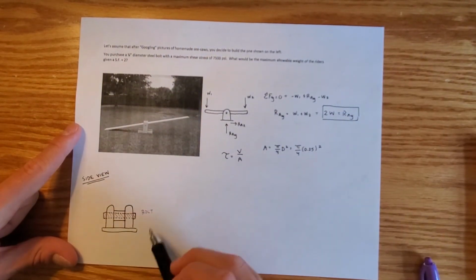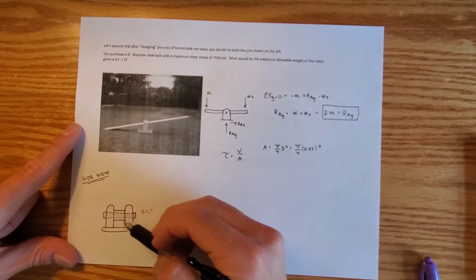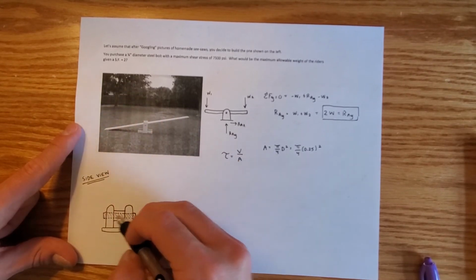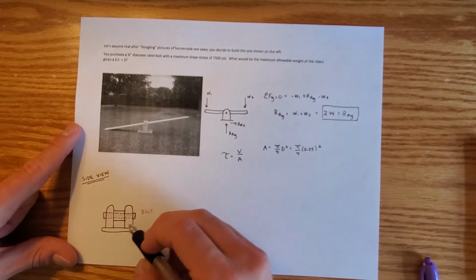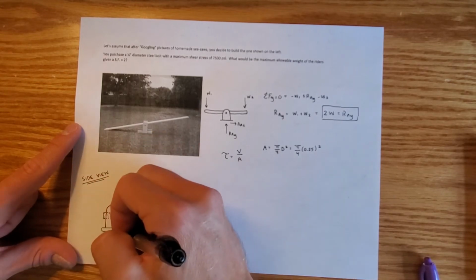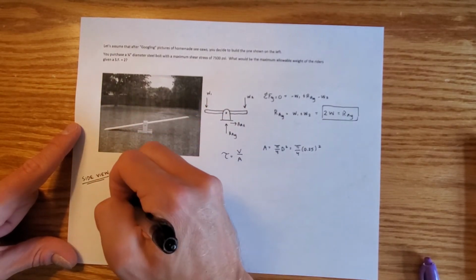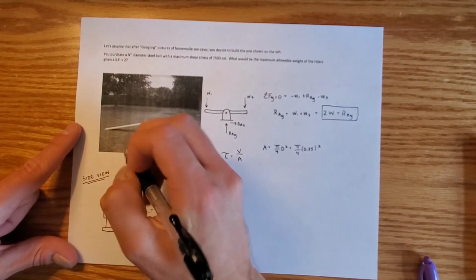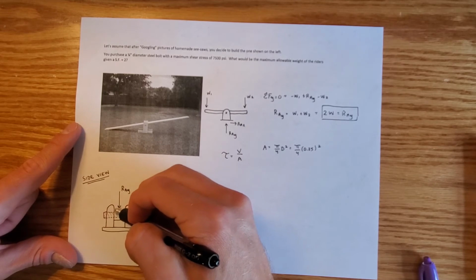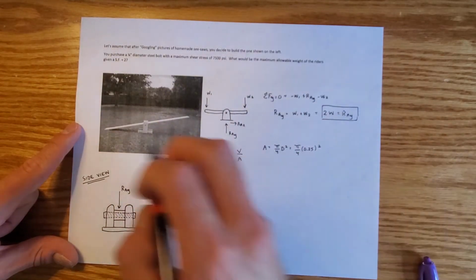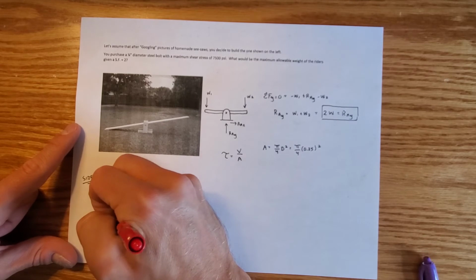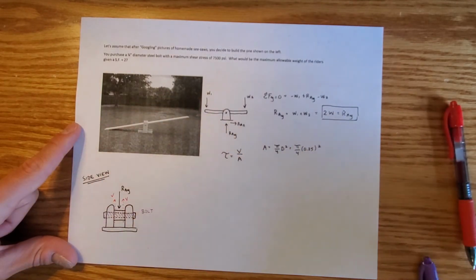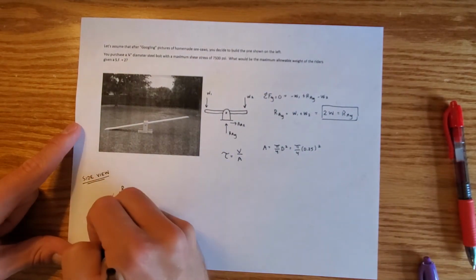So I've drawn a side view of our seesaw, and what we can see is we've got our 2 pieces of wood on the outside, our piece of wood in the middle, that is what people sit on, and we've got the bolt that's holding everything together. Now, because RAY is more or less the force that's being applied to the bolt via the seesaw, we see that our bolt can pretty much fail along these 2 points right here. So because of that, we call these 2 things our shear forces. So again, we have double shear.